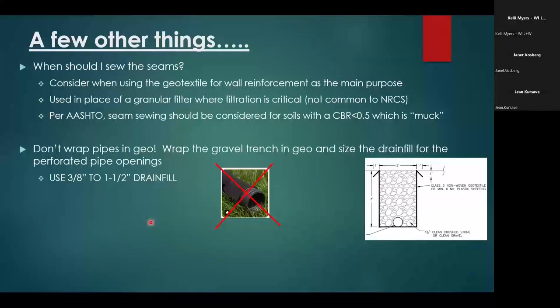Another thing about geotextiles, you don't want to be wrapping the pipe, tile sock, or taking a perforated tile and wrapping it in geotextile. It's just not a good practice, and the manufacturers of the geotextile would completely agree with that. The preferable option is wrapping the trench in geotextile and leaving the pipe unwrapped, and then just putting granular material. You get far better drainage.